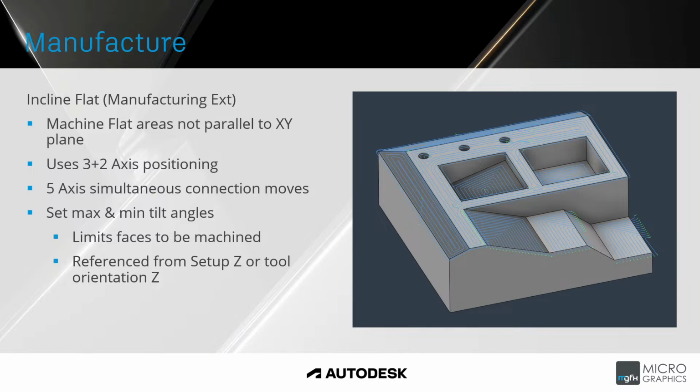With this, you can also set your maximum and minimum tilt angles. So how far away are you tilting from either your setup Z or your tool orientation Z axis. And this limits the faces to be machined.